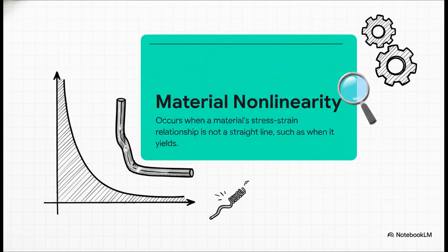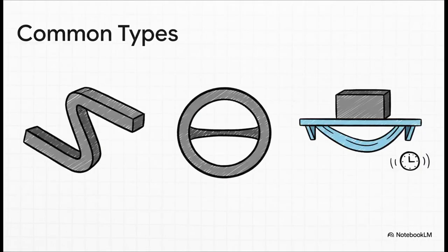Once a material yields, it's changed forever. It deforms permanently, and its stiffness is never the same. This covers all sorts of things. It's the permanent bending you see in a metal car frame after a crash. That's plasticity. It's also that unique, super stretchy behavior of a rubber seal or an O-ring. That's called hyperelasticity. It can even include things that happen over time, like creep, where a plastic dashboard slowly starts to sag under its own weight on hot summer days.